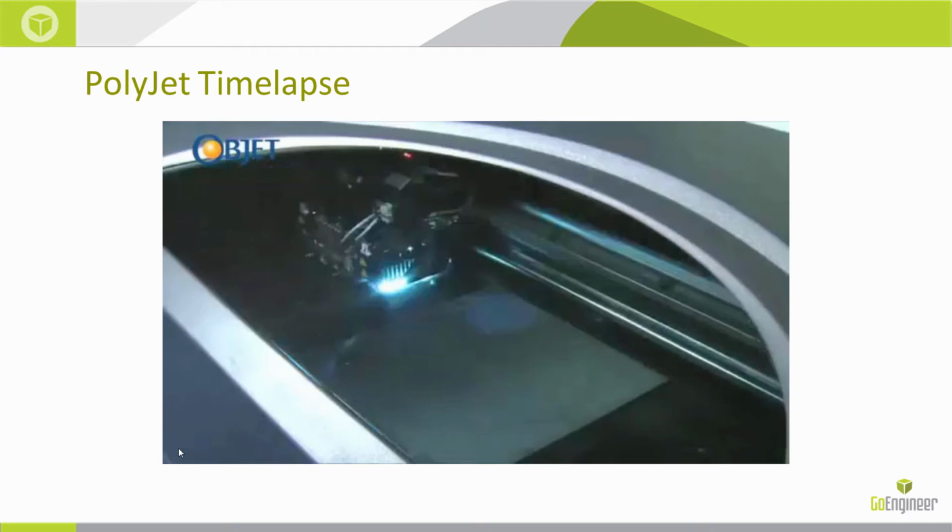Well, on the PolyJet machine, the finest resolution in Z is given as 16 microns, which is about 6/10,000ths of an inch. So the print head is going to sweep across the build platform, and it's going to deposit droplets of material. It's going to follow it up with a UV flood lamp that cures all of that material at the same time.